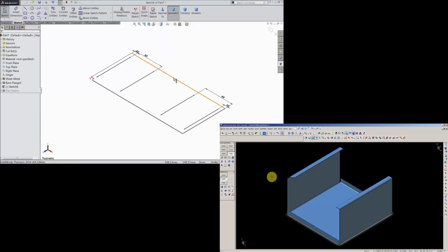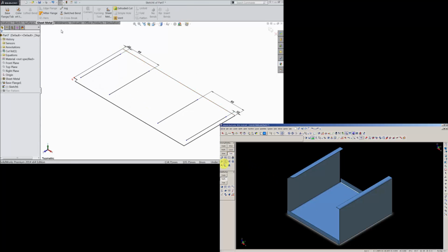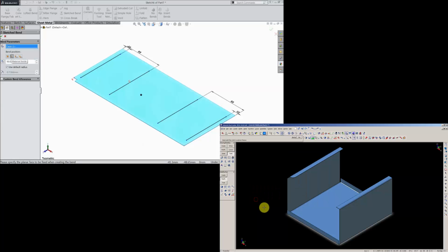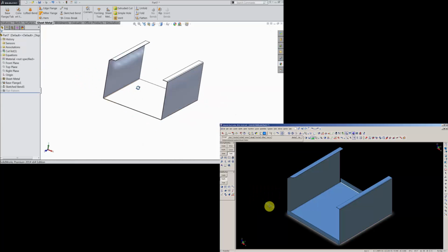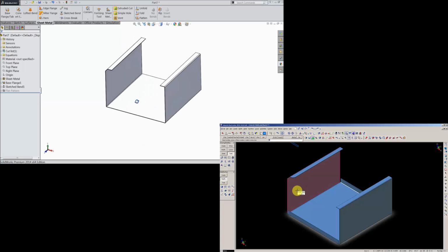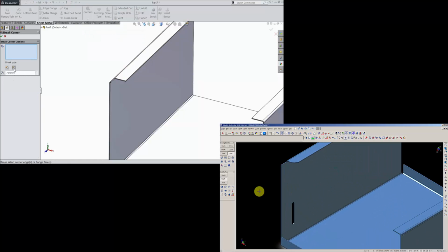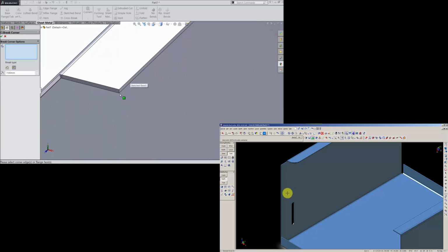Select. Now let's go to sheet metal and select sketched bend. Now here we have to select the first face. We selected face. Now these 4 lines selected, see the arrow direction showing upward 90 degree and the material inside, select OK. Now see it is automatically bent. That's it. We will add some corner trim, select fillet 7 mm and select this corner. OK.